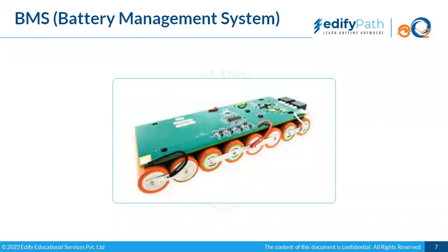So the BMS will always assure that the battery is not charged more than the end voltage and not discharged lower than the end voltage, and at the same time it will also help in balancing of the battery. It will take care of thermal management, and it would also be utilized for communication and tracking the movement of the battery.